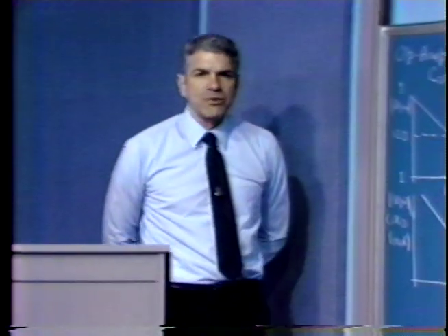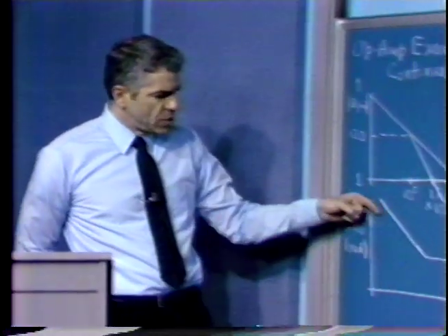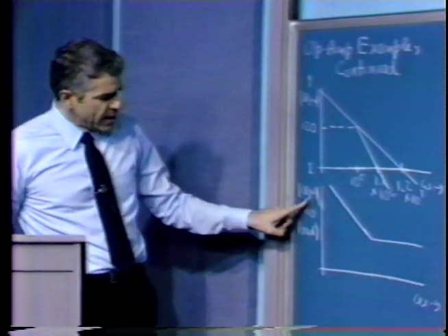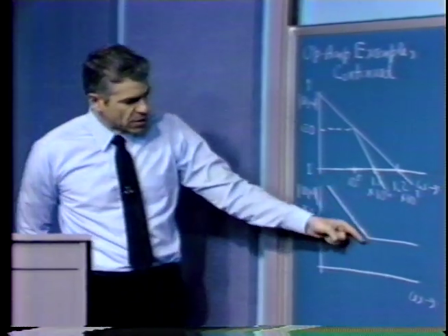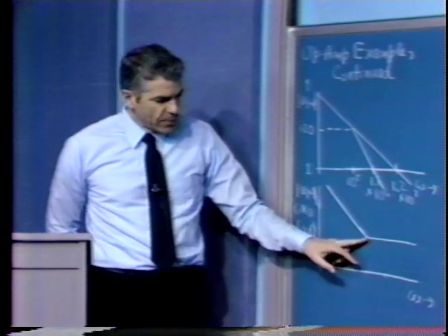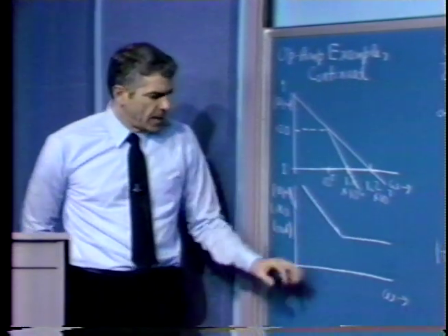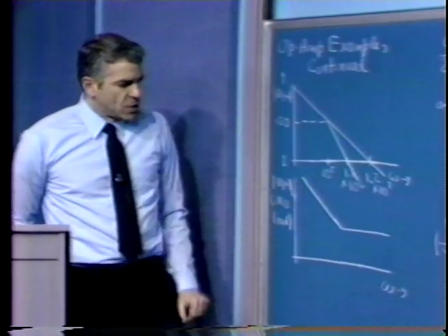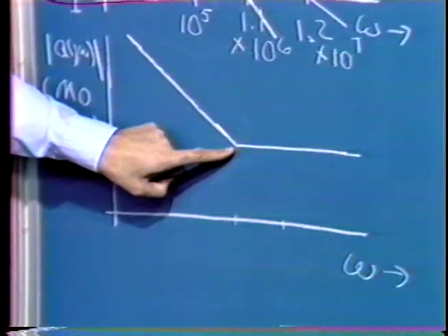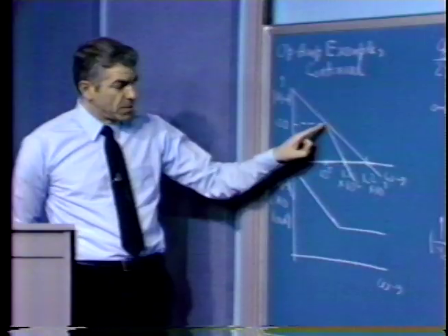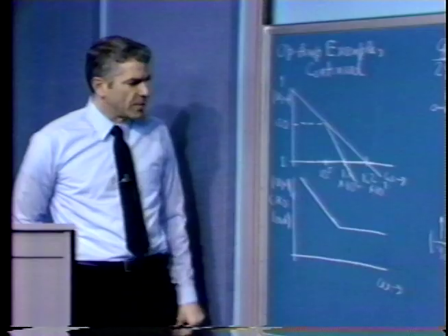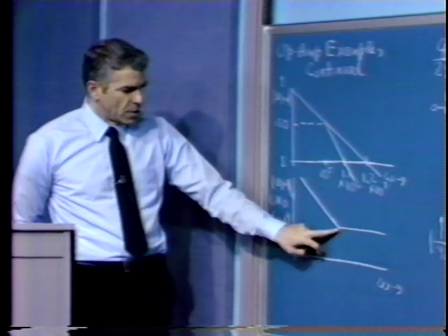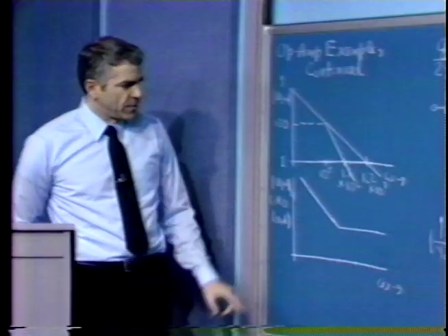Well, how might we improve the situation? The thing to do is to attempt to make the open loop transfer function of the amplifier in the absence of load include a zero. In other words, start out with an open loop transfer function that rolls off as 1 over s at low frequencies, but then at some higher frequency flattens out. If we can add a zero, we presumably could use that zero to somehow offset the effects of the pole that we get when we add capacitive loading. We might, for example, attempt to line up the zero in the unloaded open loop transfer function with the pole.